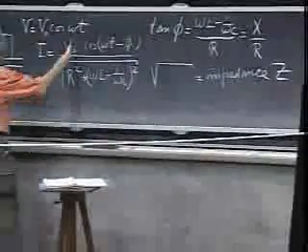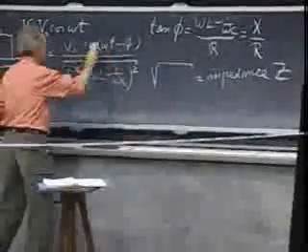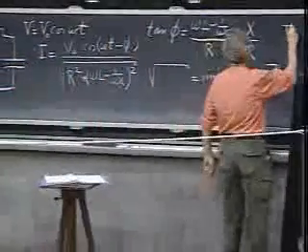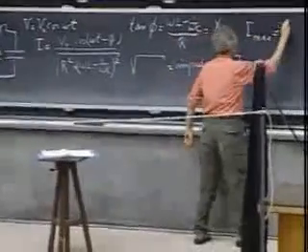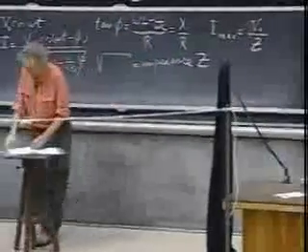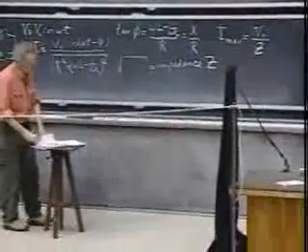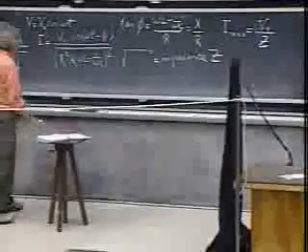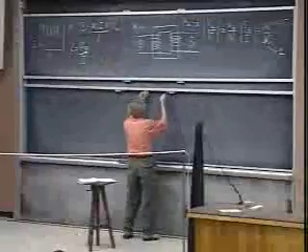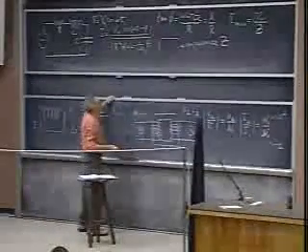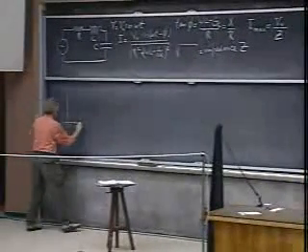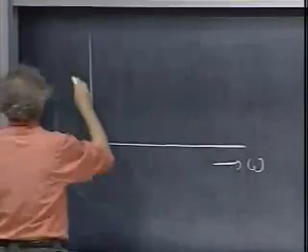And so the maximum current that you can have, the current is of course oscillating with angular frequency omega. The maximum value that you can have for the current, which I call I max, is then V0 divided by Z. Then the cosine term is either plus or minus 1. I can plot now this I max as a function of frequency. So here is frequency, and here is I max.